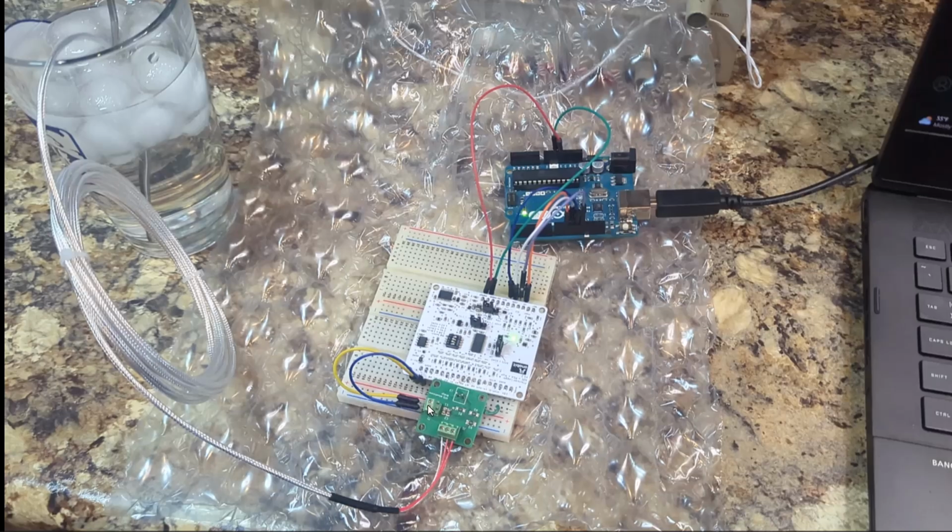You can see my excitation voltage is connected directly to the board. So this is where the board outputs its reference voltage that the ADC uses. So for this measurement, I'm going to get the ratiometric cancellation, and I do a short calibration of the ADC to eliminate offset voltages. So I'm really priming my circuit to make a very accurate measurement.